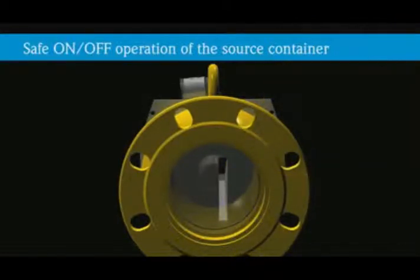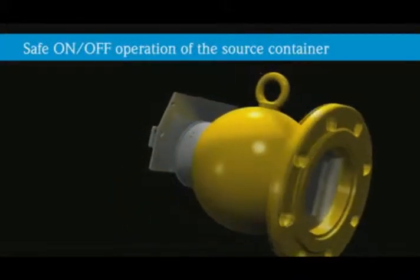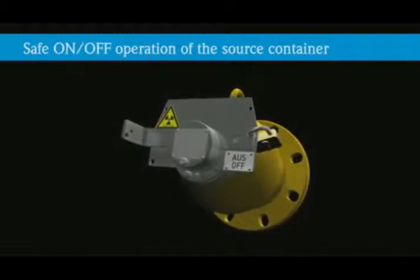In the off position, the screening material covers the source and also prevents the emission of radiation towards the flange. The off position is needed during transport or if the tank or reactor must be accessed for revision purposes. The on-off position is optionally fixed by a lock or locking bolt. Radiation can only be emitted if the source is in the on position. The unambiguous fixation of the position guarantees safe operation.